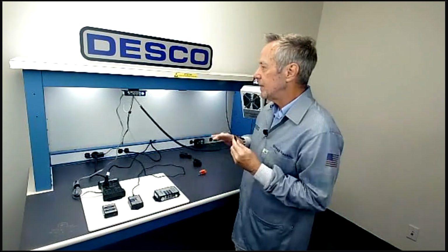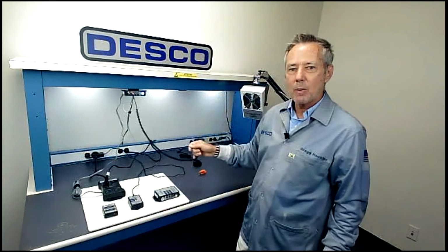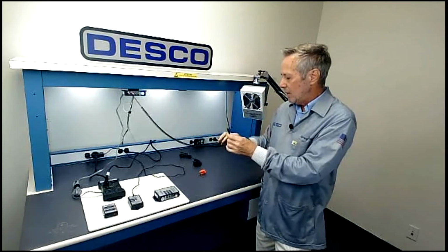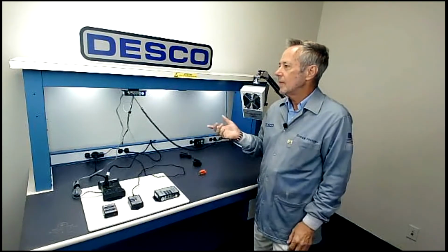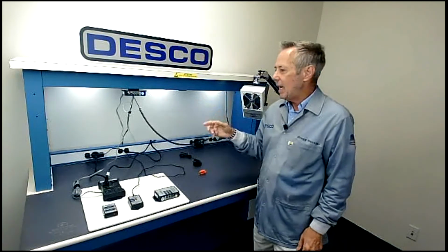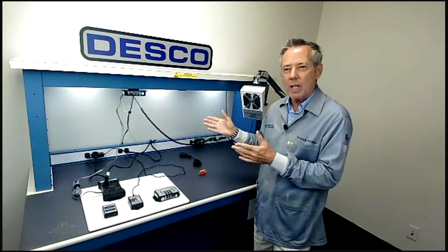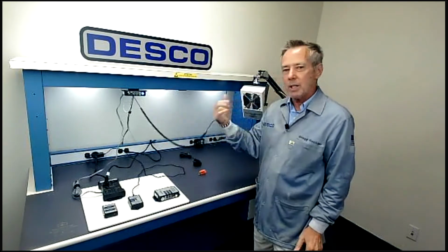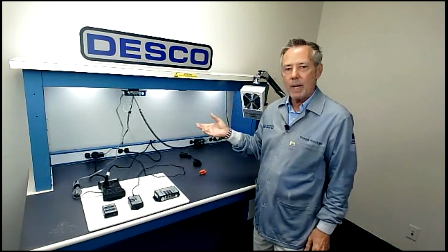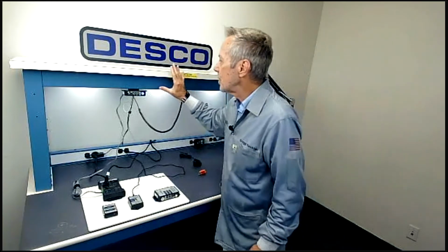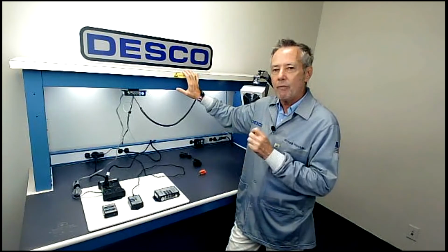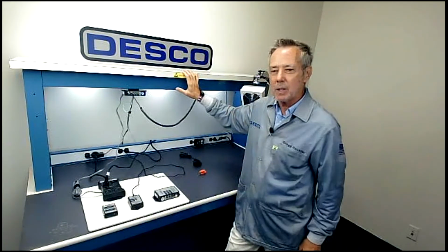If I fail, you'll hear the relay kick in and the monitor alarms, and it shut my ionizer off. When I have a good connection, the relay kicks in, and there's a little bit of delay in there just because of the design of the way it works. You need a little bit of delay for that circuit to work. But as soon as you make a good connection with your human body, that relay kicks in in less than 2 seconds, and you're ready to go again. So if you're looking for a foolproof way of making sure that person is grounded before they start to work, this monitor is the way to go.